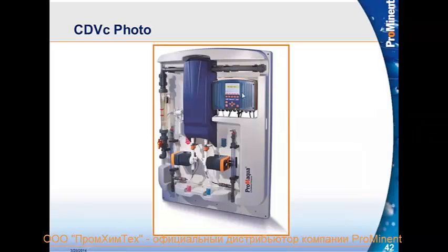Bypass water system, which is regulated in the PLC, as well as the pumps are regulated. And inside is a reactor, and I'll show you what the reactor looks like here shortly. Static mixer, where the water mixes with the chlorine dioxide solution, and then out into your process at whatever predetermined part per million residual you decide upon.